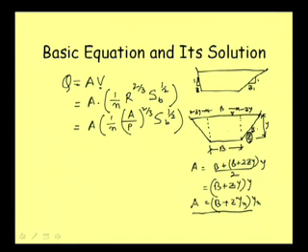That way we can have almost equal side slope on both sides. And if it is man-made, definitely if we are giving lining, then for our convenience we can make similar slope on both sides.